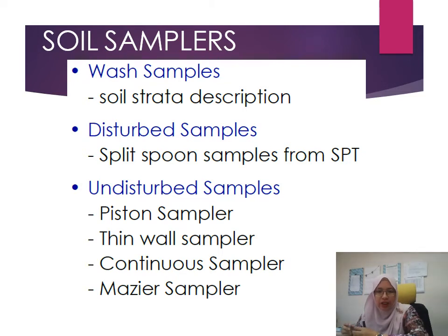If it is a disturbed sample, it means that soil properties like the structure and moisture content are not well preserved. For disturbed samples, there are types of laboratory testing suitable for that kind of sample, like checking the grading, the plastic limit or liquid limit of the soil sample, the density, or compaction testing. Undisturbed samples are more for the mechanical characteristics of the soil, such as the strength and the compressibility of the soil.